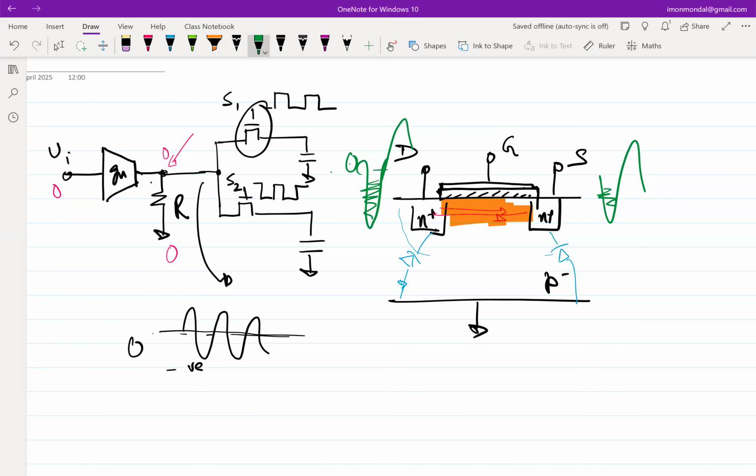Right? And more importantly, which doesn't get captured in your simulation as much, there can be issues of latch up. I have not talked about latch up, but whenever you have current flowing into the body, it can generate. Your body is also not like a hard ground, right? It also has resistances because this is lowly doped P. Right?